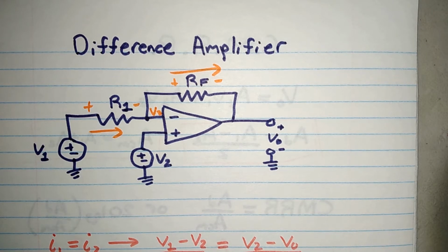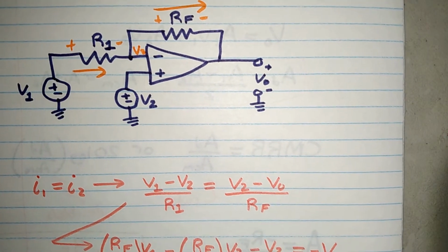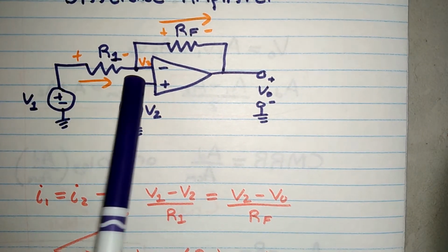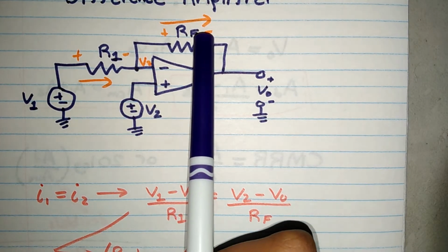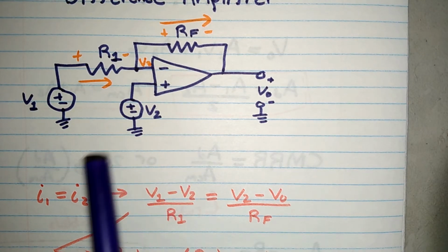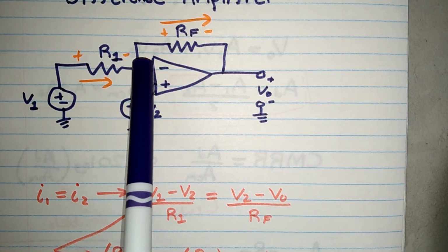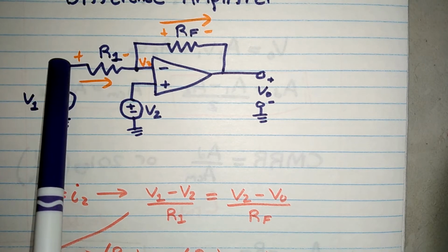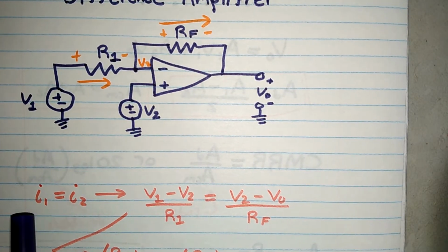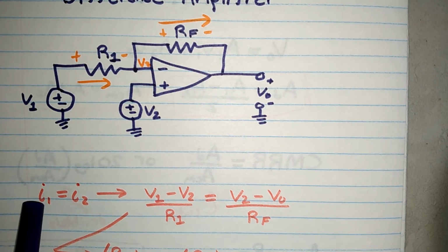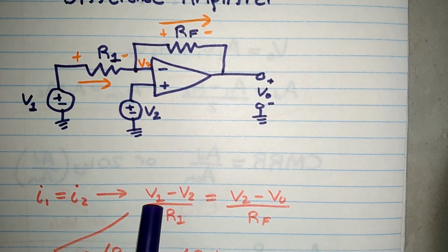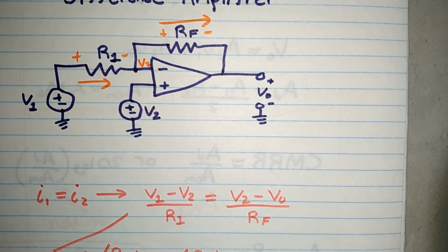Okay, so if we do the same thing as we did for the negative feedback op-amp, we're going to take our current through the top part here, and by op-amp rule number 1, no current goes into the op-amp, so we can define positive and negative for the two voltage drops and currents I1 and I2. Nodal analysis says I1 must equal I2, and so using Ohm's law, how can I derive I1?